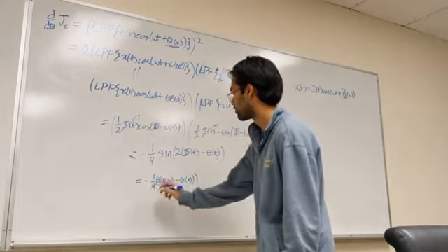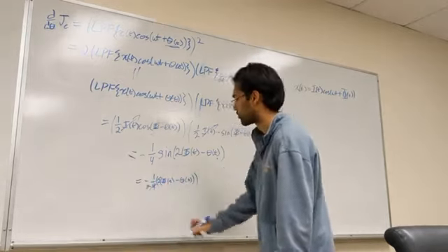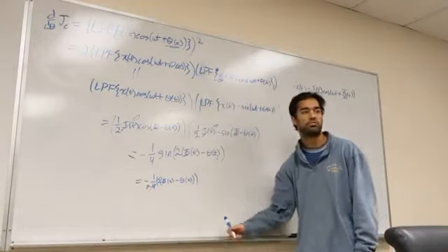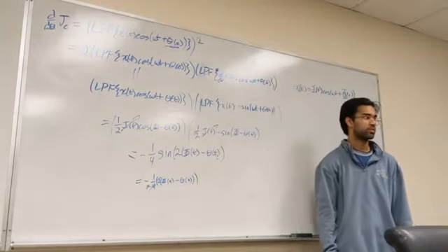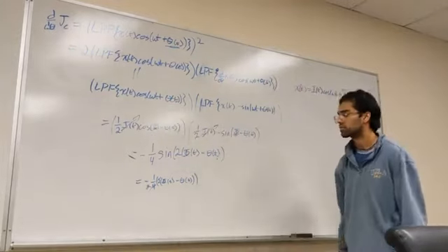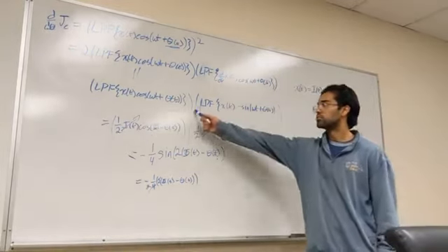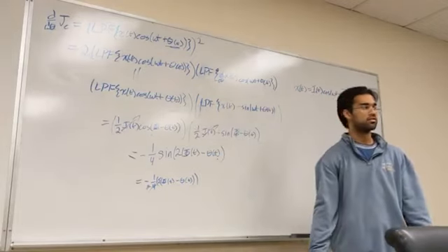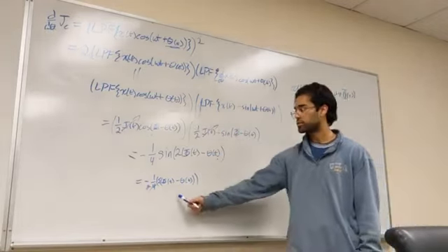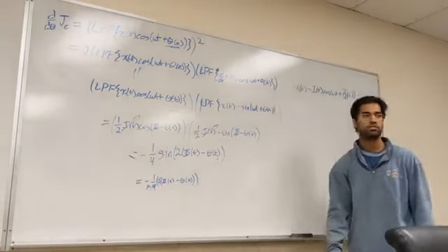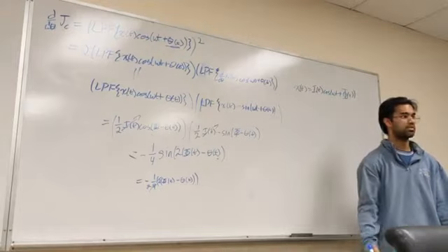Okay, that's 1/2. You're able to find the phase difference by taking the derivative. Knowing that this is just demodulating over here, and then multiplying the two signals together, we know we can physically realize this. We can physically realize finding some kind of error function, our phase offset. And that's kind of what the Costas loop is.